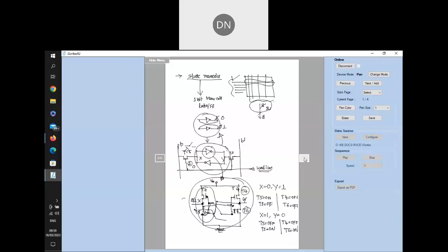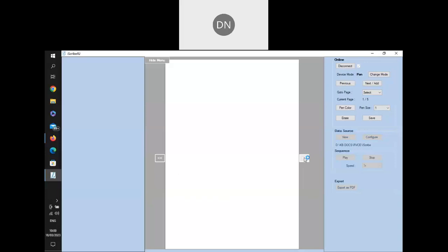Now, apart from this, you have one more transistor here, which is already available, that is T1, and one more transistor similar to this is connected here. So totally 4 plus 2. How many transistors do we have? Totally 6 transistors are required to design one memory cell. So if I want to implement one bit of SRAM memory, I require space for 6 transistors.